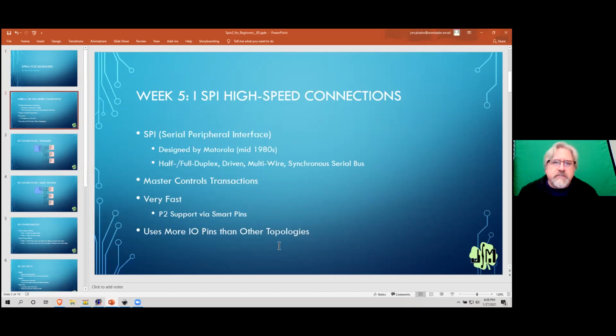You'll see a lot of devices that use SPI, even if you weren't aware that that was happening, that are not even intelligent devices. Things like shift registers and really simple chips like that, that can use simple digital state machines. They work really, really fast. And that is one of the advantages of SPI. It's very fast. Many microcontrollers that are available today have SPI hardware built into them.